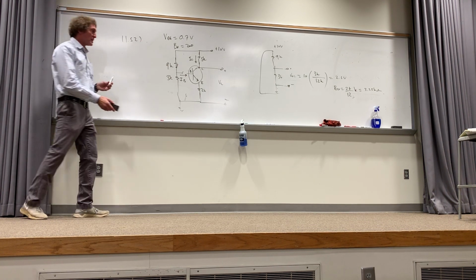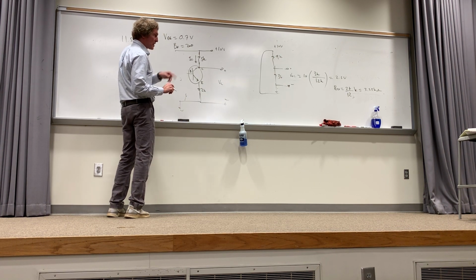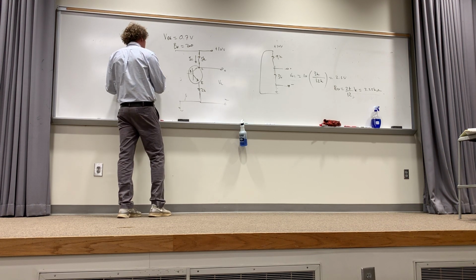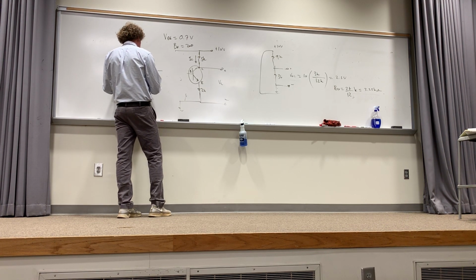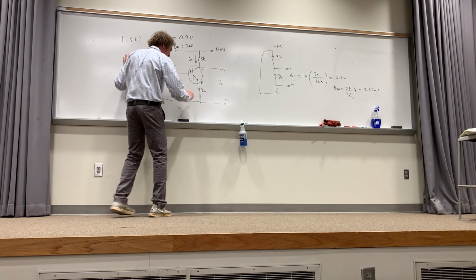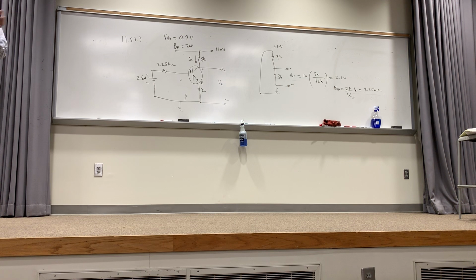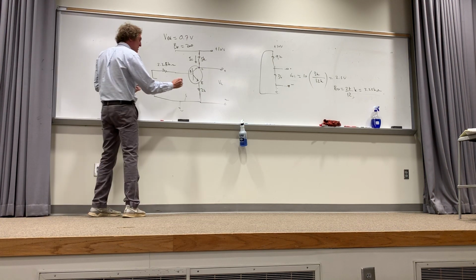Can everybody see that? So when I'm doing that, these 2 get taken out. And now I put in that Thevenin equivalent circuit. It's an actual voltage here of plus to minus 2.5 volts, and it's got a resistance here of 2.25K ohms. Do y'all agree? Remember, this is how you do this kind of problem. Hint, I can't be more clear. You're getting a Thevenin equivalent source for the resistive division. Now, once you have that, can I find my base current here?